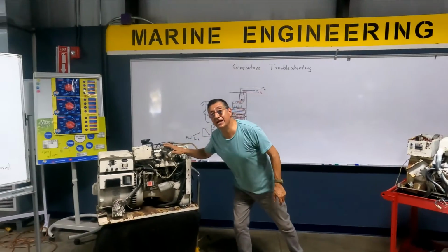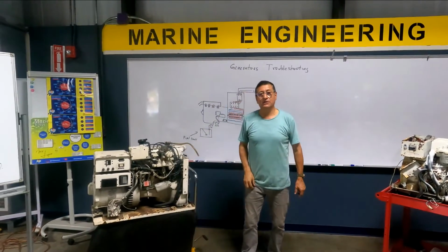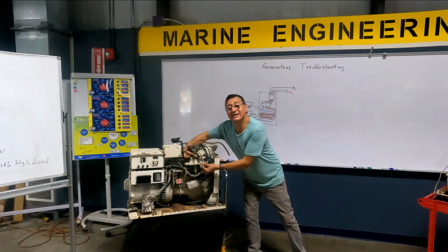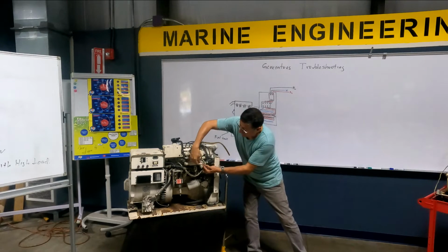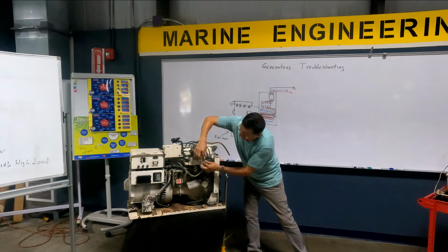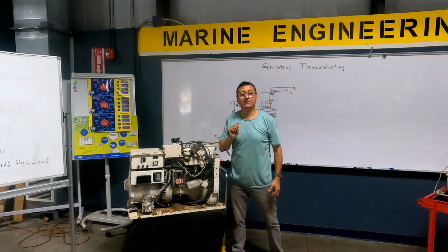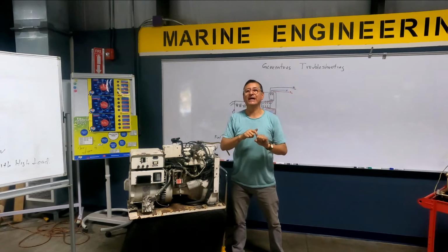In this generator, carbureted, you can start and stop the generator when you interrupt this solenoid. This is the idle solenoid. You disconnect the power in the idle solenoid, and what happens with the fuel entering the carburetor? That solenoid closes and no more fuel enters.